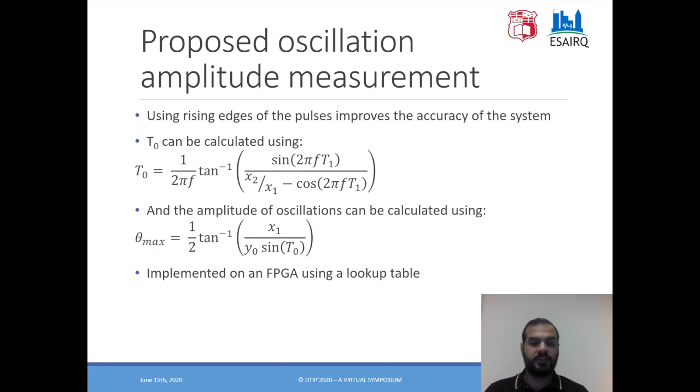The previous measurement system described relied on both the rising edge and falling edge of the photodiode signal. The rise time and fall time will not exactly be symmetrical, which means that an error would be introduced into the system. As discussed previously, a small error in the system will have a large effect on the measurement.